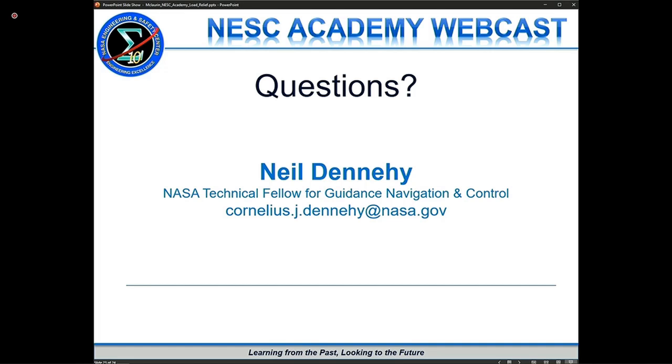Yeah, that's a very good question. Everything that we've shown here is applied to a specific class of large launch vehicles that are typically relatively slowly ascending multi-stage systems intended to put payloads in orbit. There's a lot of literature on how those linear equations are built, but the fundamental assumptions are that the angular rates are very small, on the order of a degree or 2 per second, that the angles of attack are close to zero, and that the thrust vector control angles are close to zero.